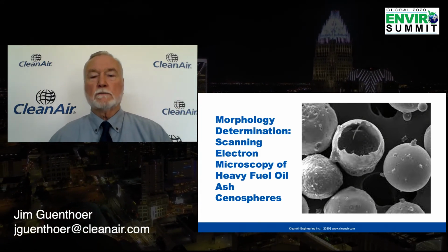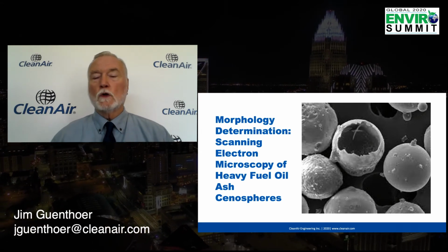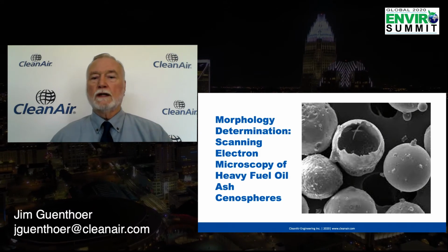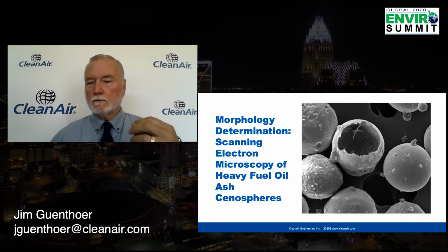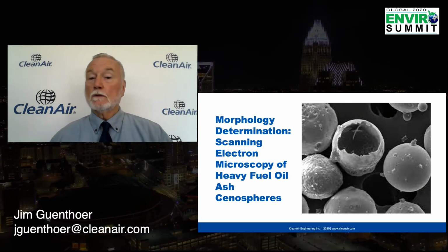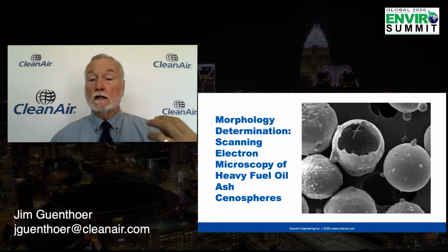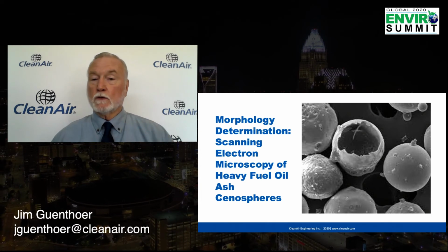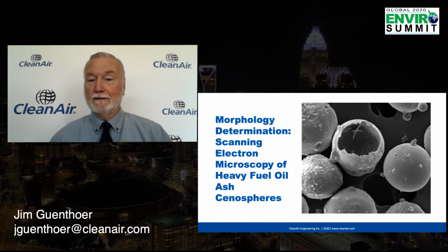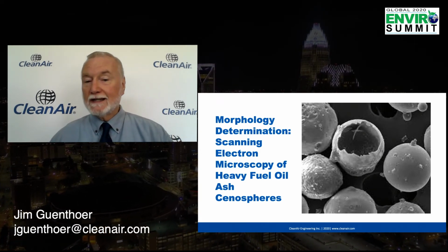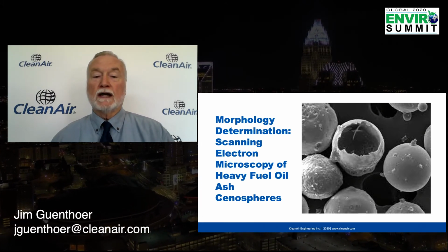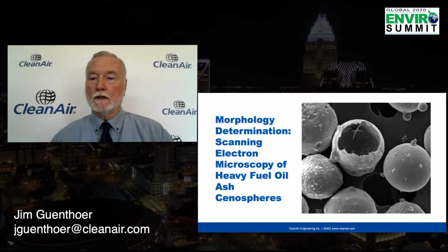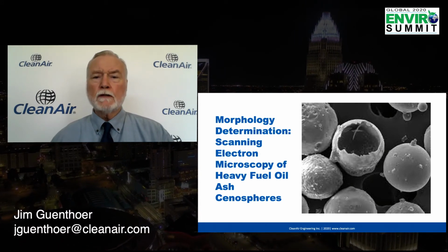This is a classic picture of heavy fuel oil that's burned extensively in the Middle East. When heavy fuel oil is combusted, it makes what are called cenospheres, which, as you can see, are hollow spheres. So even though they're larger and spheroidal, they're hollow, so they're less dense than you would think looking at them. But that's a classic heavy fuel oil particle.